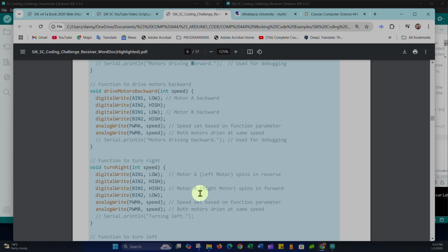If I need to turn right, whatever way you're turning, you always want that wheel to go backwards, in reverse, and you want the other wheel, in this case the left wheel, to go forward. So this is saying that this is the left motor, but this in fact must be the right motor, because this one is going backwards, because again, remember, when input 1 is low and input 2 is high on a motor, that's driving in reverse.